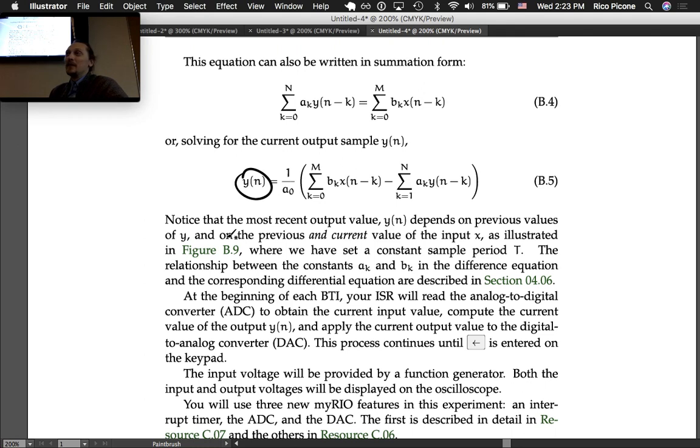Now we're going to digitize it to more values than that, so you have to decide which level the voltage is. So are we going to approximate it as being 0.1 volts coming in, 0.12 volts, 0.15 volts, whatever it is, and then we have to output something that's digitized as well. But it has to be turned into an analog signal at that point, because it's going to interact with the real world. So the calculation happens digitally,